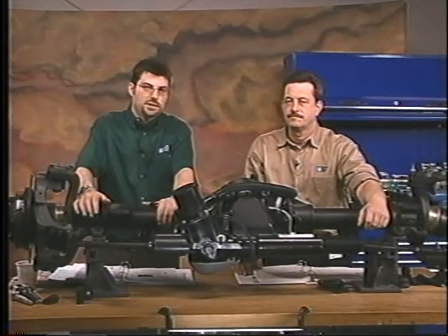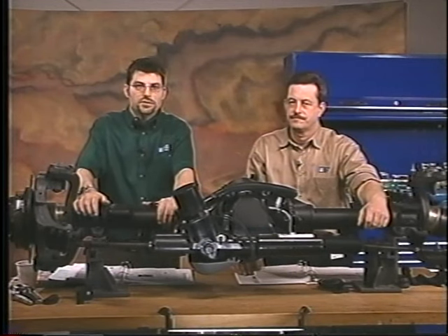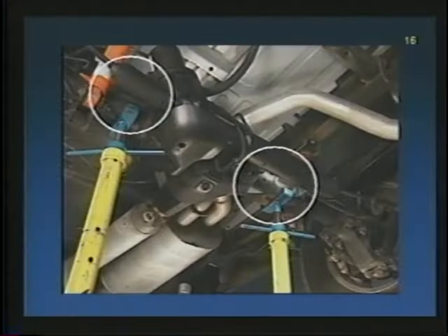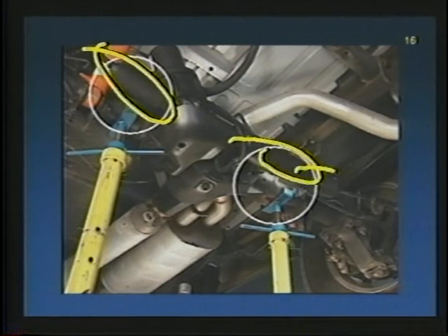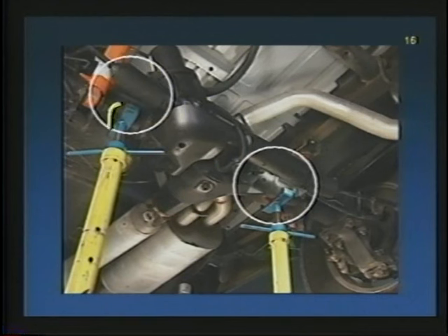Well, this leads us to a tech tip that we have for you on page 1-7. It has to do with lifting and jacking the vehicle. Now, a couple things to keep in mind. If you're using one of those old school twin post in-ground hoists, where you get that cradle that comes up and grabs the rear axle, you've got to make sure you don't contact the skid plate. You've got to make sure you don't lift the vehicle by the actuator or the inner tie rods. You've got to make sure you contact it by the axle housing itself.